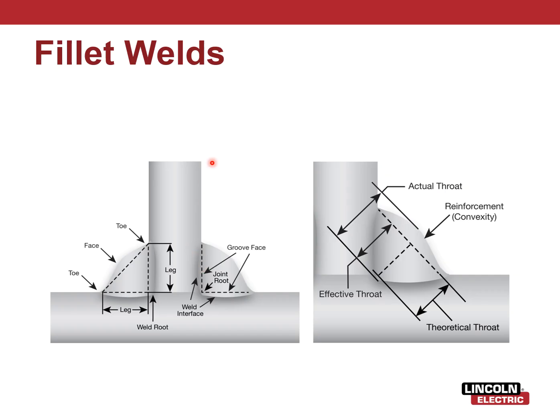So if you measured your T-joint, put like a soapstone, boom, 3/8 here, and then measure this way and 3/8 here, that's where your toes should be meeting. Okay, so that's what the leg is. This measurement right here, from the toe to the root, basically, both sides.